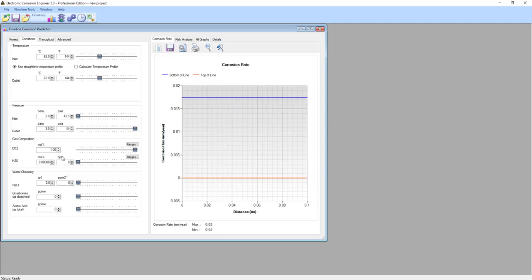As you understood, I'm not using the design data. In corrosion analysis, we always use operating data as the system is facing operating conditions most of its design life duration. The corrosion is not a sudden accident like what we do in thickness calculation of a pipe body. It requires facing corrosive components during a long time to happen.